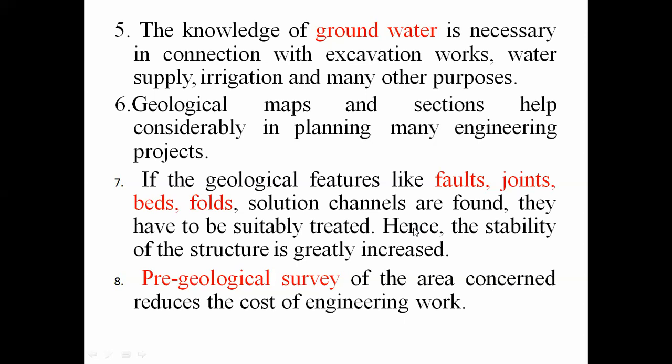But if structures are present in the site you have identified, if you have selected any site and in that site structures are present like fold, fault, joints, unconformity, then that site will be having problems in the future. Okay. So we have to identify whether structures are present in that selected site.